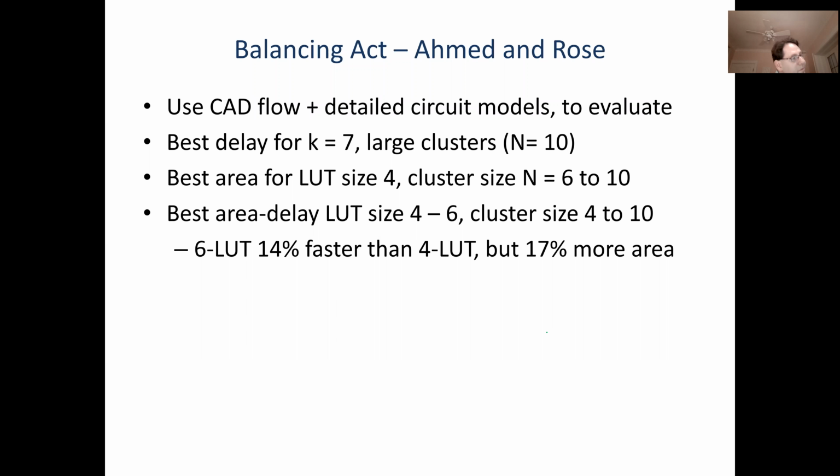Okay, so because of these complicated trade-offs, we need a full CAD flow and detailed circuit models, which is exactly what this paper did. They found the best delay is for really big LUTs, K equals 7, but they're pretty inefficient in area.